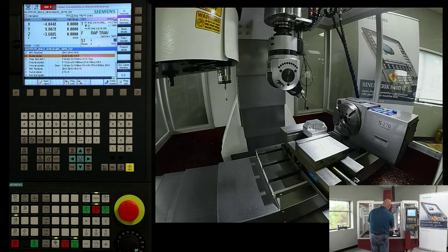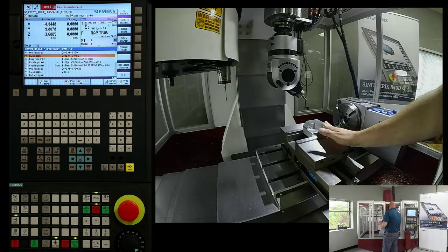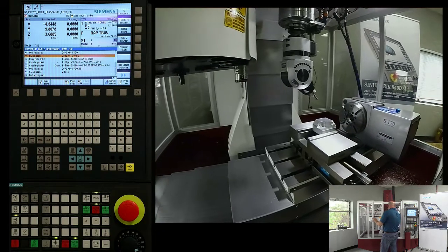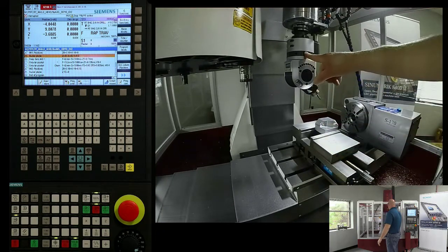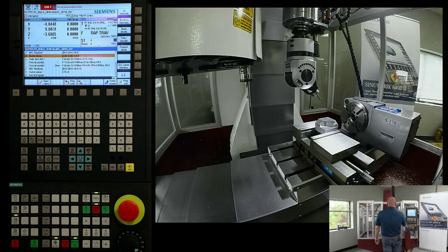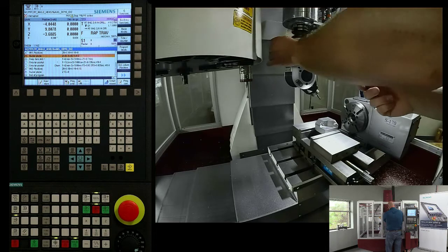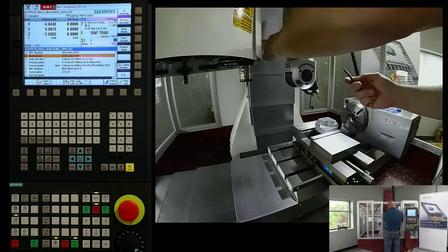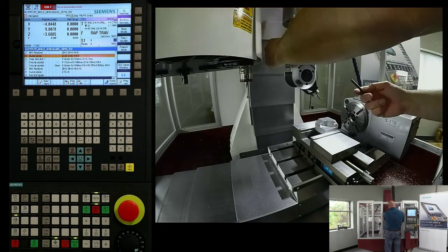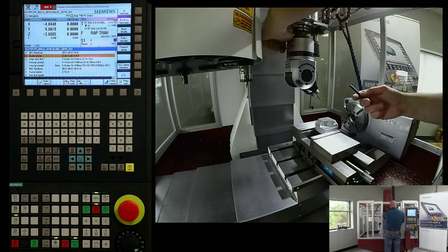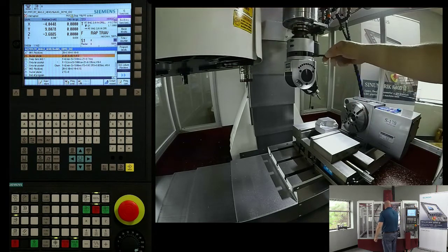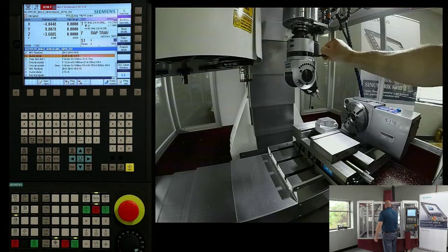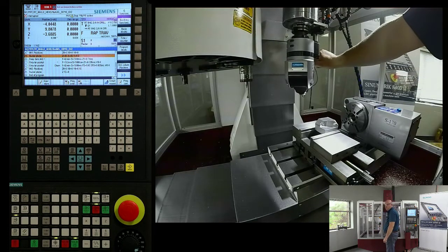Now in this case, we did our first operation. It's telling me on the control I now need to change my orientation. So for this scenario, I've got to get over to this hole. One of the things it's asking me to do is rotate about my C-axis on the display to 315 degrees. So when I want to rotate this head, I'm going to loosen up this collar. There's 2 bolts that loosen up the collar. And then I'm going to spin or adjust the tool to this orientation.